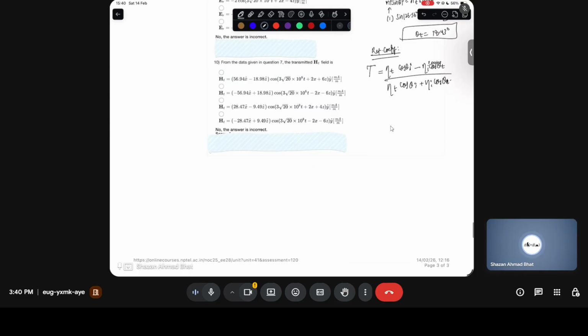This is basically reflection, and these are impedances of the transmitted media and incident media. This is exactly the same as what I talked about earlier when you had the impedances. When the electromagnetic wave hits a load, which is RL, and you get a reflection, you use it to compute the reflection coefficient there. And how much was that?